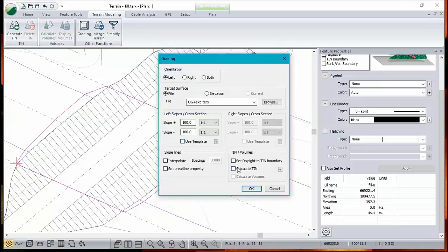Okay, so for this fill, we're going down at, let's say, 1.5 to 1. There shouldn't be anything cutting upwards. It should all be negative slope, downward fill. Okay, and again, I want lots of little lines. I meant to point out where those were. Those are the lines there you can see in the background, 1/2 meter apart. That's from the excavation cut. And the fill is going to have similar projected lines going downwards.